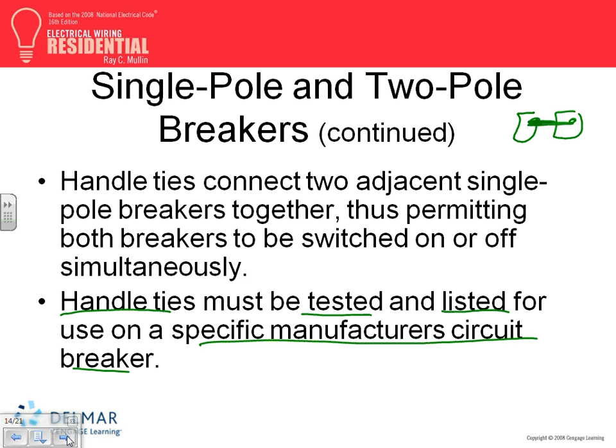If you have a three-pole circuit breaker, you put the three-pole circuit breaker on a three-phase load. A three-phase load has one circuit breaker, three-pole, with one handle that goes into the three-phase circuit breaker. So keep this in mind.